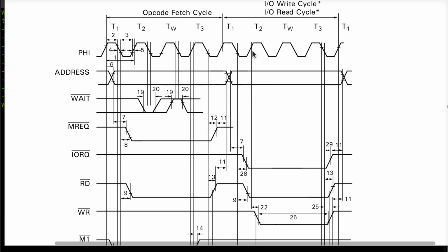Now, sometimes you don't have enough clock edges in here to put a regular old Verilog HDL synchronizer circuit, which is a shift register normally used to deal with metastability problems. In this case, we don't necessarily have to worry about metastability because the things I'm going to use as inputs in my circuit design already are guaranteed to have a setup and a hold time around the edges that I'm looking at in here. Okay, so I want to make sure it's perfectly clear to anyone watching this. This is not a synchronizer to solve any metastability problems. Okay, just so we're 100% clear.